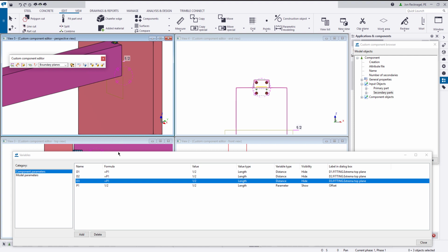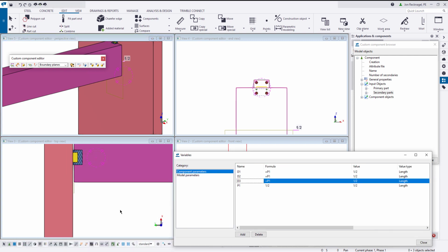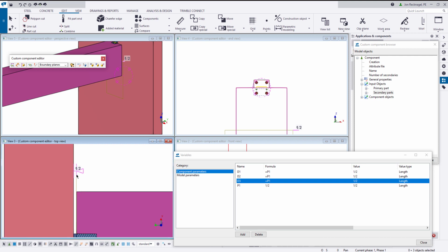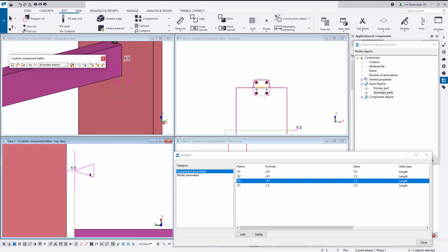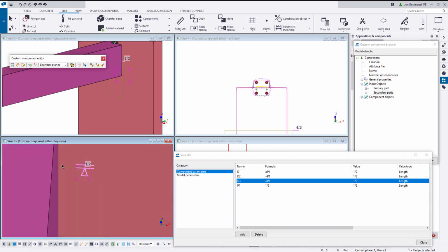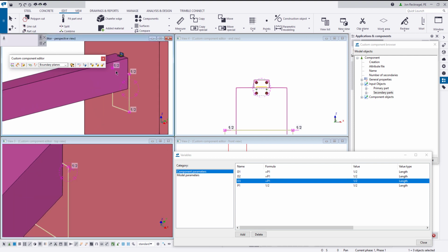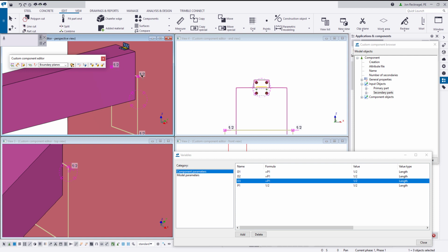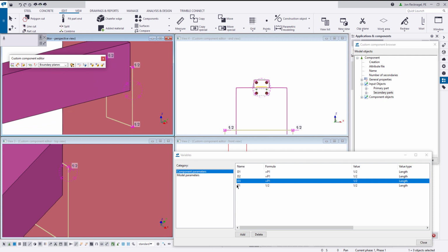And as I'm doing that, if we make this view maybe a little smaller here, we can see that now we have a nice half-inch gap. And you can see these little arrows here, these little magenta arrows. These are our bindings that we've created. So each of these, if I click on the fitting, you can see them better probably in this 3D view up here. This is going to be like our D1, D2, and D3 bindings that we've just created.